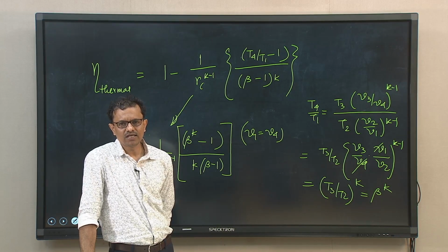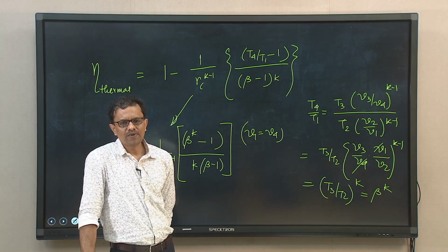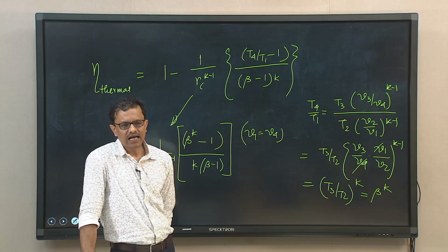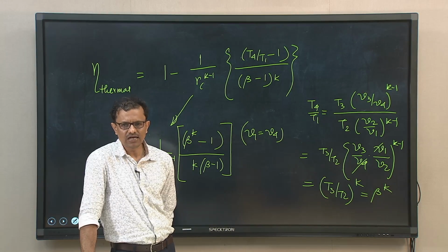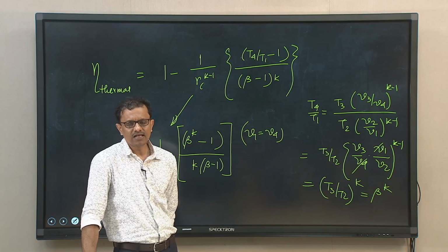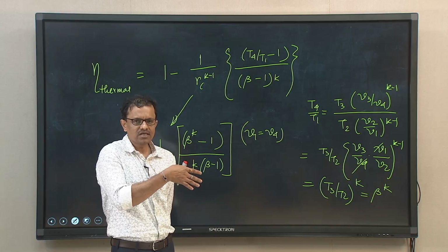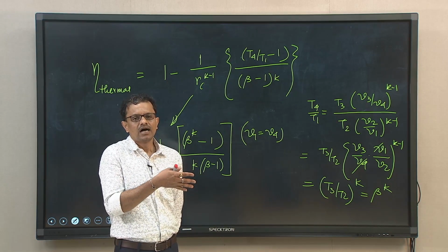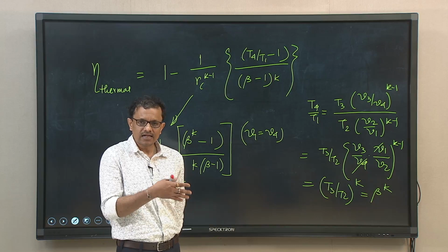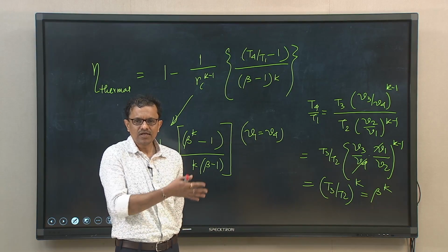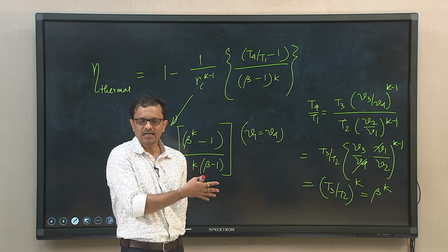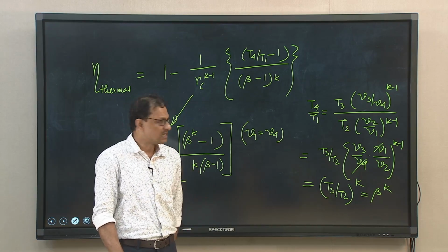Now, one thing I forgot to tell you: to compare the performance of a 4-stroke cycle SI engine, we have discussed an air standard cycle, called the Otto cycle. Similarly, the processes of a 4-stroke cycle CI engine are approximated by an air standard cycle, because we have applied ideal gas relations and assumed that the working substance is air, and that cycle is known as the diesel cycle.